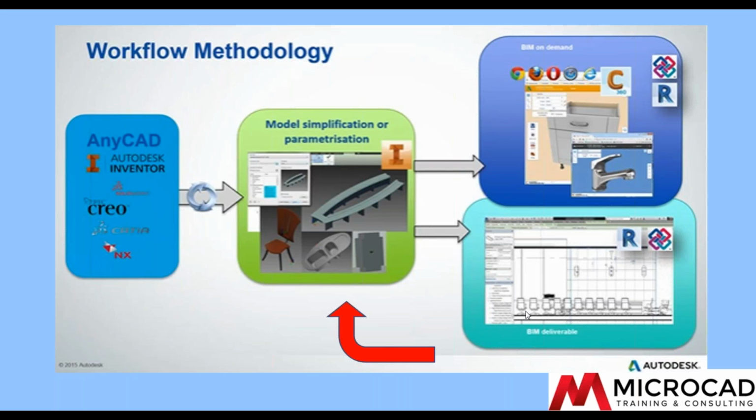With Inventor, that is easy. Inventor can link the Revit model into the product design and let the product designer work with the architect's geometry. Because it's an associative link, if the Revit model changes, the Inventor model will change also. And this is a closed loop. Your updated Inventor model can become a new Revit family, which can update the family in the architect's Revit model. This way, everyone sees the most recent data.